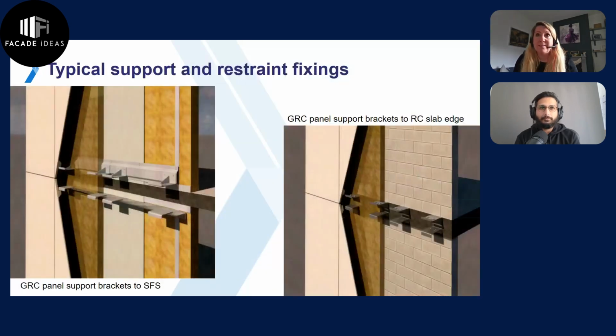So how we would hang that would obviously depend on the primary structure and where we will position those, but typically it's a bracket and rail system, a very strong, thick bracket and rail system as opposed to some of the other systems, granted, but it is simply put into place as large panels as well. So very useful for tight sites, as most brick slip facade systems are, and we don't really need to use cranes with this particular system, so we can use spider cranes. We can perhaps look at a solution of lifting off the ground as well, so a fairly easy system to install.